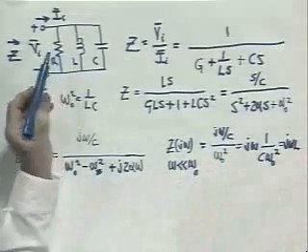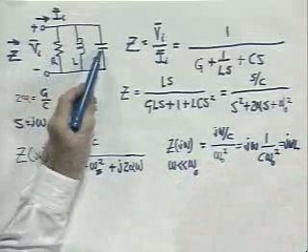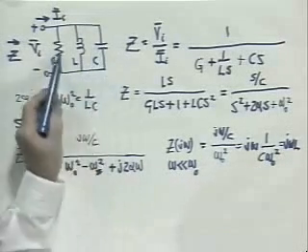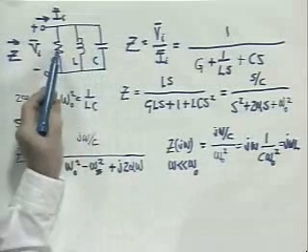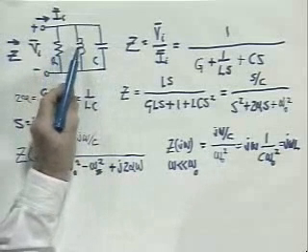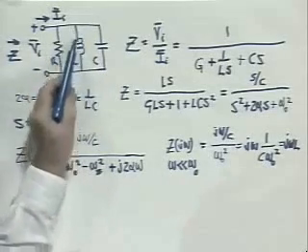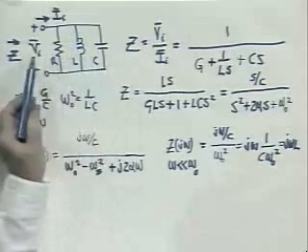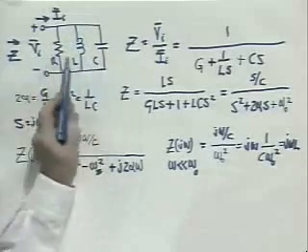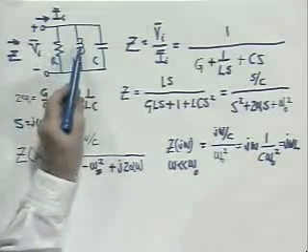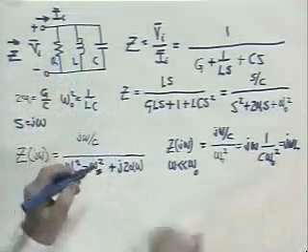Does that make sense? Well, the impedance of the capacitor varies like 1 over omega. So as we go to lower and lower frequencies, this gets bigger and bigger. The impedance of the resistor is fixed at R. The impedance of the inductor varies as omega. So I go to lower and lower frequencies, omega L gets smaller and smaller, and the inductor dominates the impedance at low frequencies. It's like having two large resistors in parallel with a very small one. The only one that matters is the small one, so it looks like an inductor.